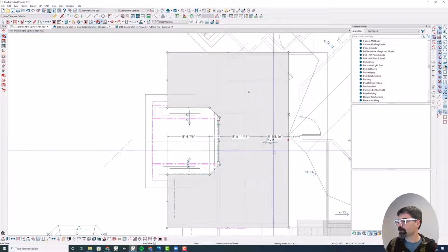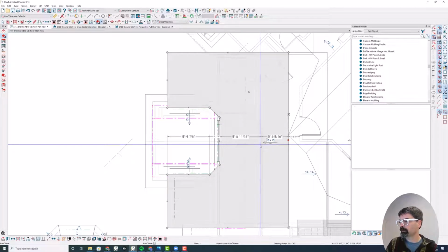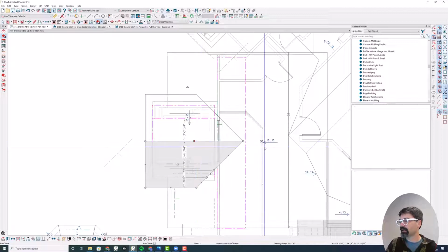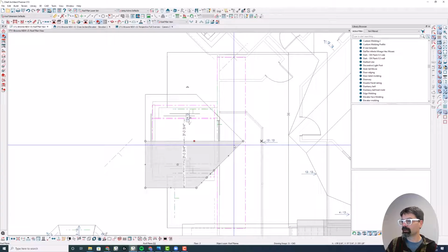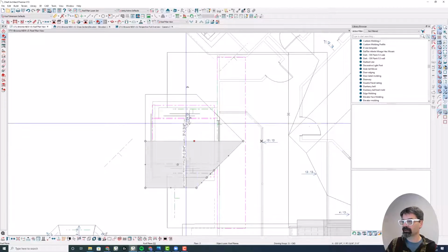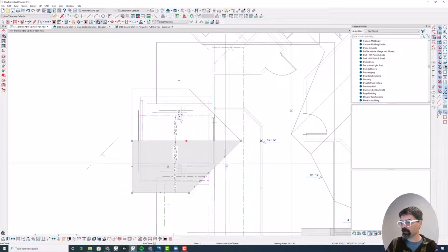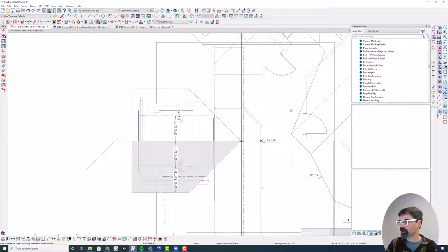So I've selected the receiving plane, the plane that will be intersected, and then I'm going to click on the line that will be doing the intersecting. And there, in the 3D world, is where the two will meet. Chief Architect has figured out the elevations of things, the pitches of things, and that, in plan view, is where that will meet. So for my roof plane, I'm going to simplify this polyline, and I'm going to drag that roof out to snap to that point.